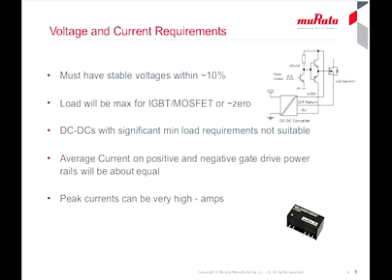We have also seen already that a high voltage swing gives higher gate drive power, so the voltages are chosen carefully. For IGBTs, they might be plus 15 volts and minus 9 volts. A silicon MOSFET could be plus 20 volts and minus 5 volts, and the latest silicon carbide type might be plus 18 volts and minus 3 volts.